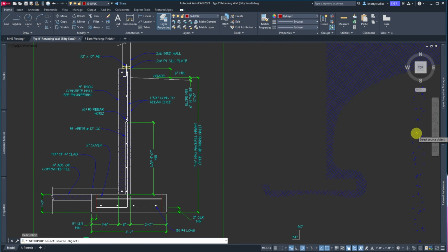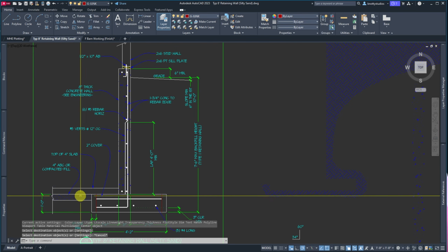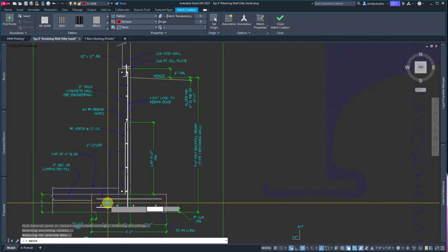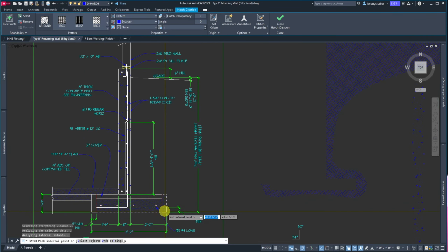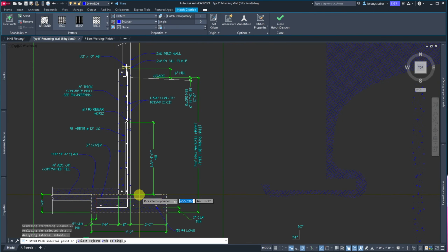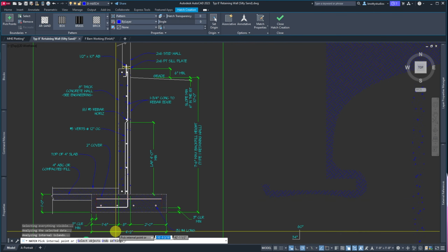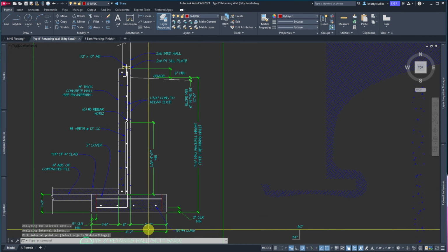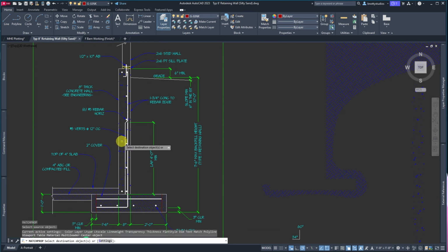Okay, so I want to change the wall, but I don't want to rehatch everything. I wouldn't have to rehatch my slab, for instance. So now I can hatch this, enter, hatch this. Oh, because of my lines that are in here, it is separating out. It'll go around dimensions, but it won't go around lines. So there's that. Now those two are separate. So MA, click that, choose my concrete and my concrete.